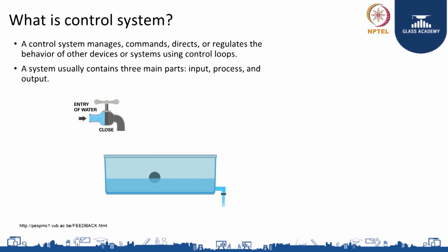On similar lines, we can use controls to maintain the light levels in the space. We know that the daylight entering from windows or skylight will keep on changing from time to time in the day or season to season. However, we would like to have a desired illuminance level on the task surface.